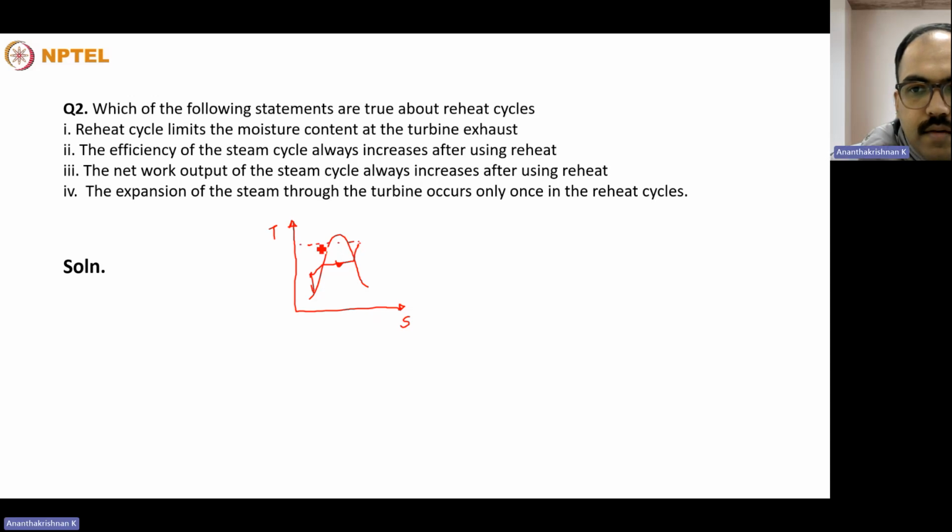and from there there will be high temperature turbine where the steam will be expanded, and then there will be a further heat addition to the same temperature, and then it will be expanded in a low pressure turbine. So as you could see, these two are constant pressure heat additions, but the initial pressure will be quite high compared to the other pressure.